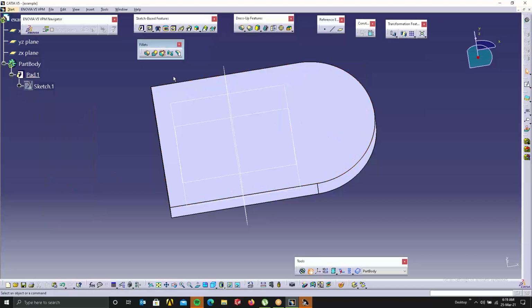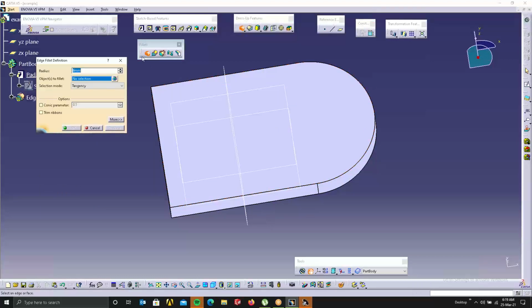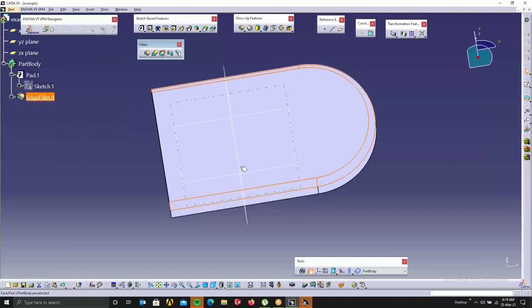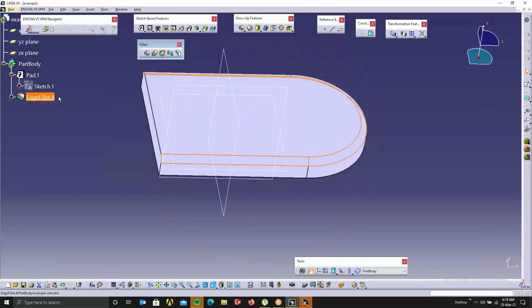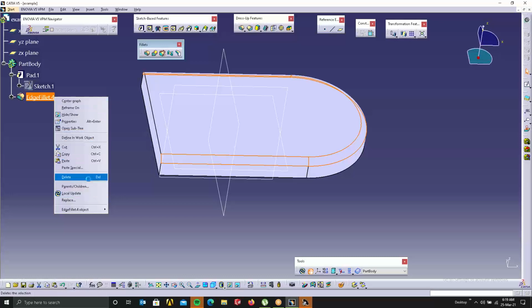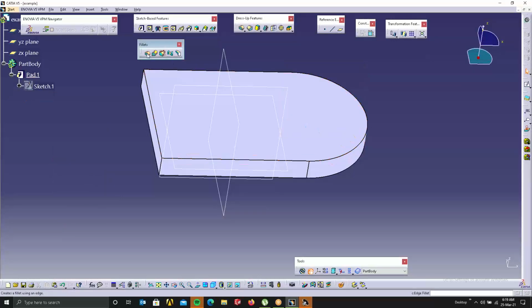Okay. So we are discussing fillets, how to do fillets. In fillets, there are different types: tangency, minimal, select, intersection with selected features. So we'll be explaining these. Tangency is basically, if you select the edge and if you have any tangent elements, all those tangent elements will be selected. So this circle is tangent to this. All the elements that are connected will be selected and a fillet will run through all of it.